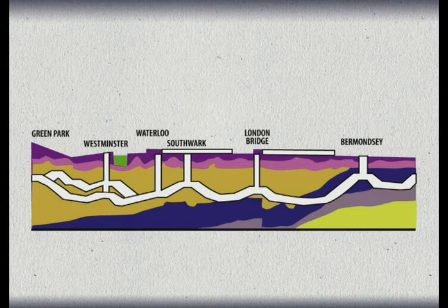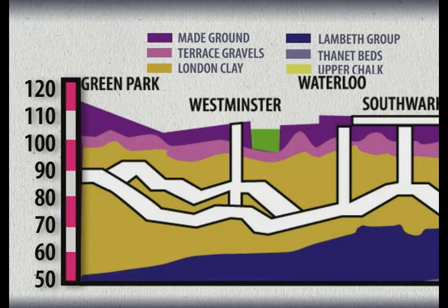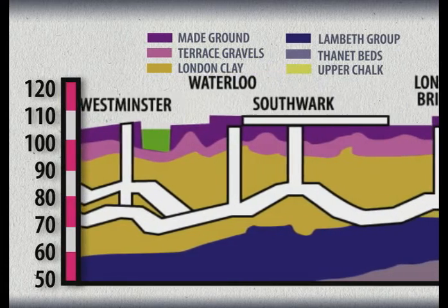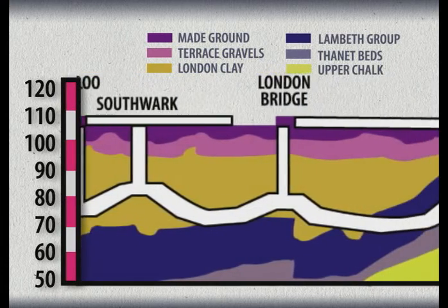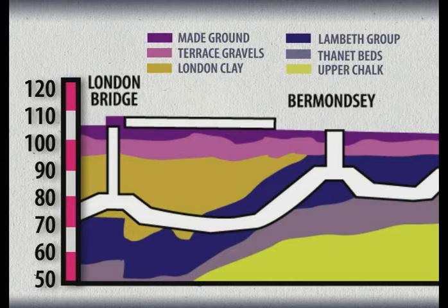Yes. Well, the north part of the tunnel is all in London clay. So it starts at Green Park, and it runs down under St James's Park through to Westminster, and all that is in this beautiful tunnelling material, the London clay, which is traditionally ideal material for tunnelling in. And then we go under the Thames at Westminster, and again we're in London clay until we come down to round about where London Bridge is, because it turns east and runs along the south bank to London Bridge,